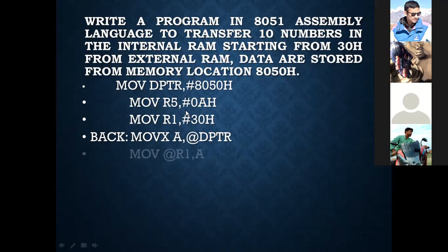Okay. So in the next one, the content is to be moved into 30H memory location. So we will use MOV @R1, A. That means the content of A register is moved to the memory location that is pointed to by R1 register, that means 30H memory location. Clear? So first data has been moved.